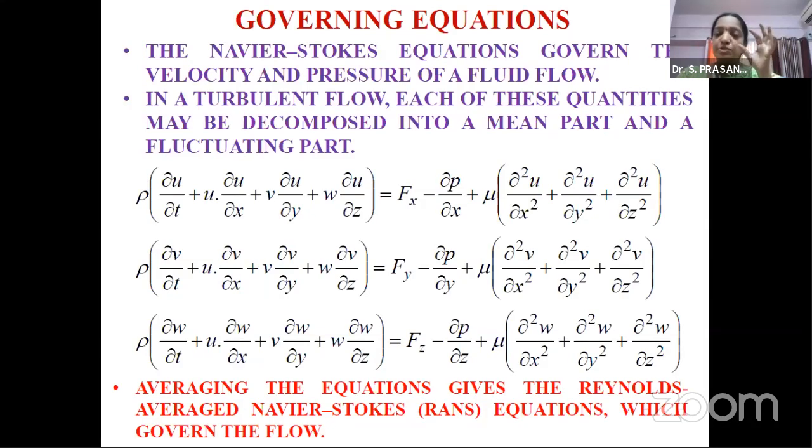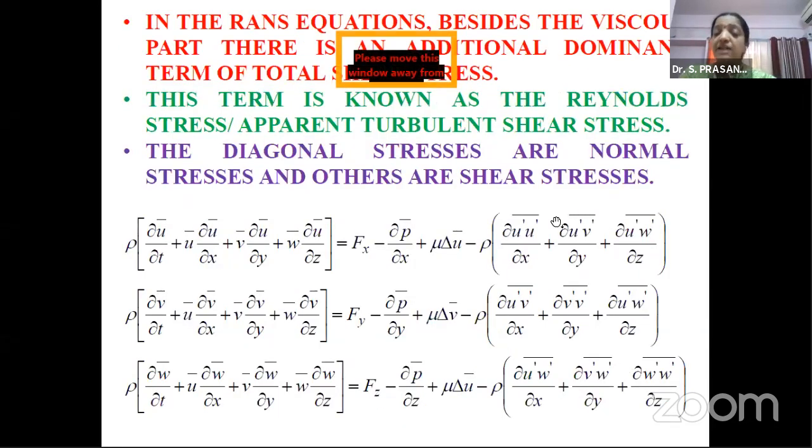All this is because we are interested only in the average components, not the fluctuating components. Most engineers are oriented towards understanding the averaged properties of the fluid. So when we apply averaging with respect to time, we encounter the Reynolds Averaged Navier-Stokes equations, which add additional terms.